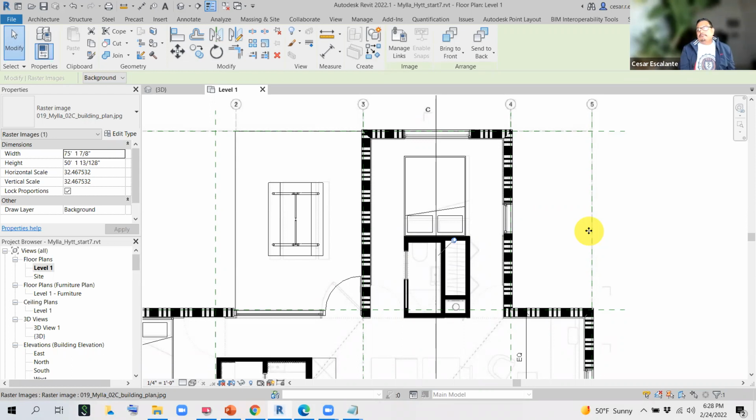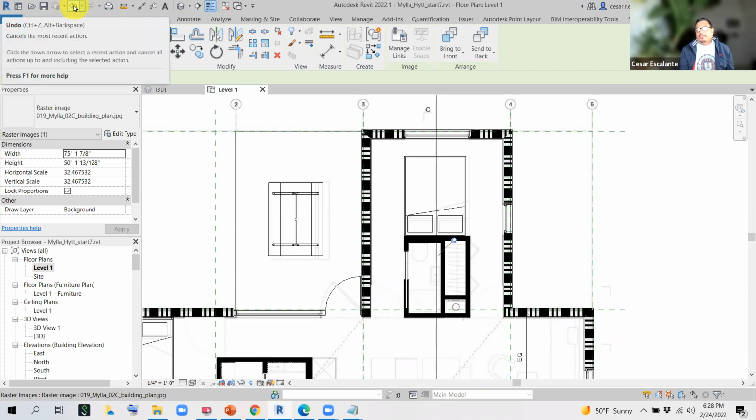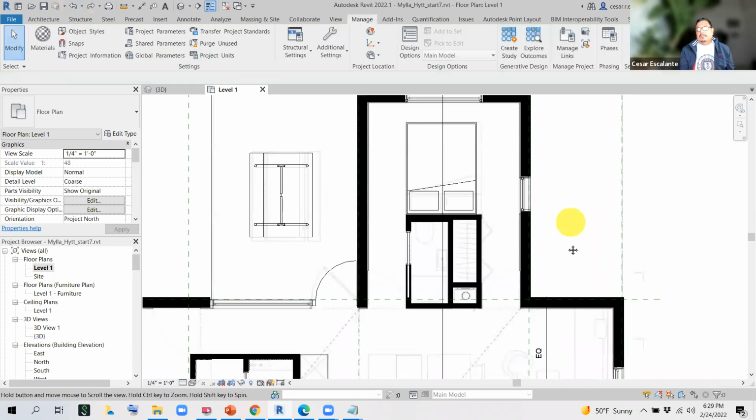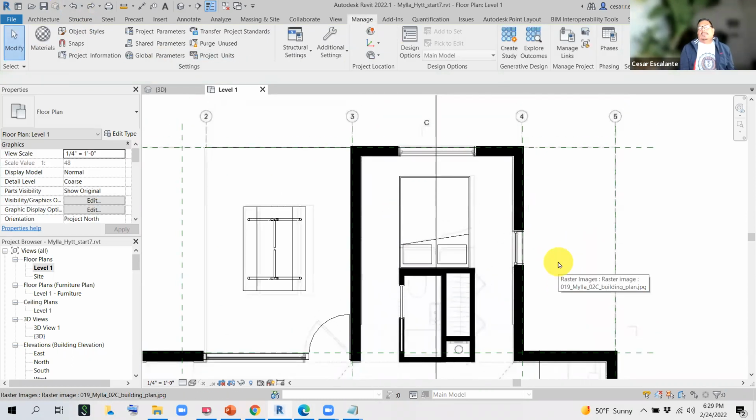So for simple commercial, this would work. For large commercial, there are a lot of problems with this hatch method, because in addition to hatches, you also need to define whether something is a smoke partition, or if it's full height.